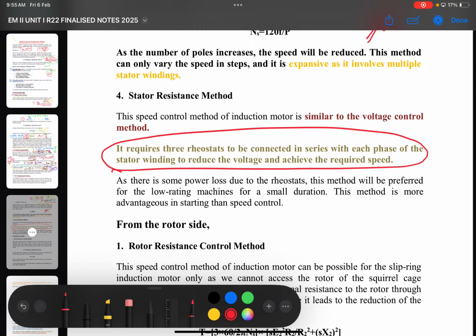What is actually happening in the internal five knob regulator? Five different speeds are there. You already discussed this in detail about the 3-point starter, how you are limiting the starting current here. At starting, we are including maximum resistance. Slowly we are removing the external resistance here.